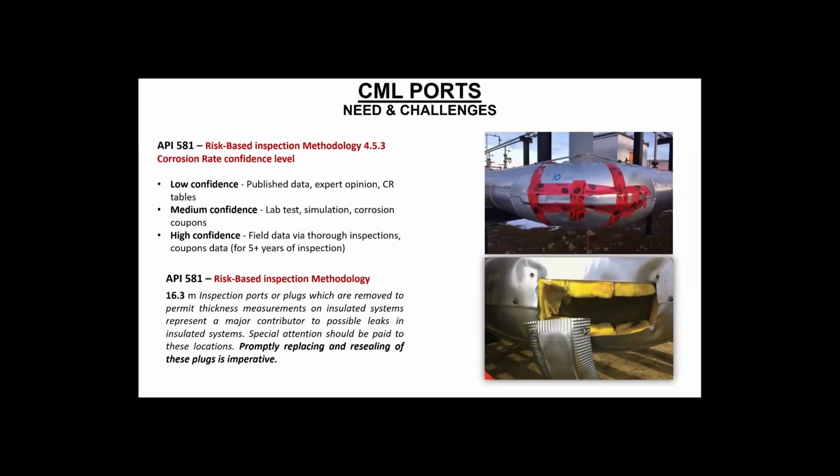So these are some of the real life examples of how moisture gateways get triggered from bad workmanship, from nature driven events, from field retrofits. So there are multiple reasons. Now another thing which is very common in real life, we see the CML points, or we call that TML ports, inspection ports. There are different names, some people call that UT ports, ultrasonic thickness points, but the concept is the same.